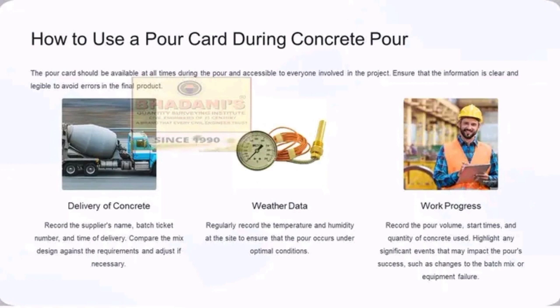Remember, in a BQ, it is elaborated in each preamble that the class of concrete that you should use, and all the specifications that you need to put in place is recorded. So you match if the concrete and the one that is there are compatible. Then you proceed with the work.